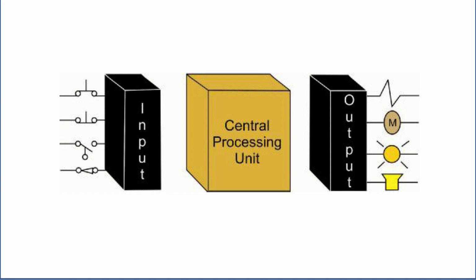Now the moment you put the Coca-Cola inside the bottle, the Coca-Cola is a dark colored liquid that will not allow that laser light to pass through it. Now whenever such a filled bottle passes, every time the bottle passes, you get a disruption in the signal. The signal will be broken. So this is a very good example where you can find whether your bottle is filled or not, and you are happy with the sensors.